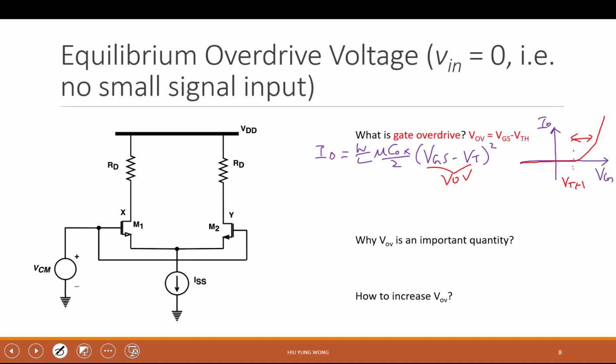It's just like the baseline. You have two transistors, you're competing with another vendor. They said they have a much larger current than yours when they bias at 1 volt. When you bias at 1 volt, yours is only half of theirs. That's not a fair comparison. You need to say, what's your threshold voltage? Maybe I already get this amount of current by having 0.1 volt overdrive. And they might actually have 0.5 volts overdrive, right? So you need to compare what is the overdrive on top of the threshold voltage, right?